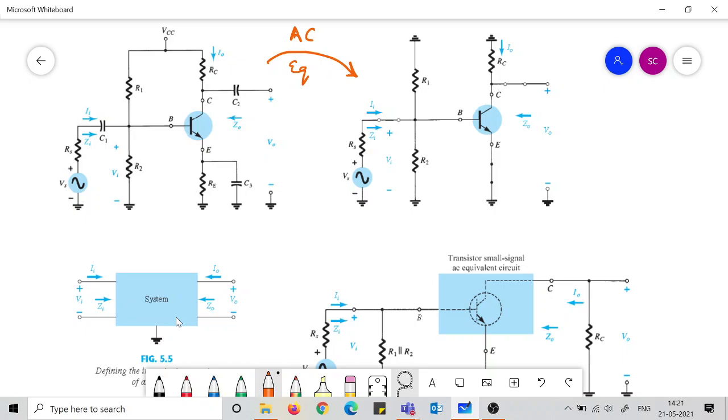So this is the input side. A similar concept is there in the output side. So when this is energized, suppose this is delivering the output now. When it is delivering the output, at the output port what will we see? We will see a voltage, and obviously a current also. So when we see this voltage and current at the output port, we can also ideate something called the output impedance, which is the impedance seen by the voltage while trying to deliver the output current.